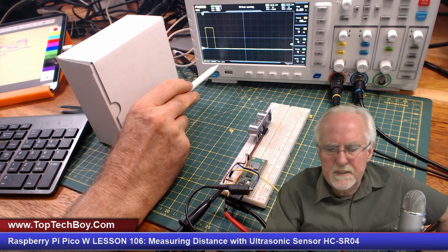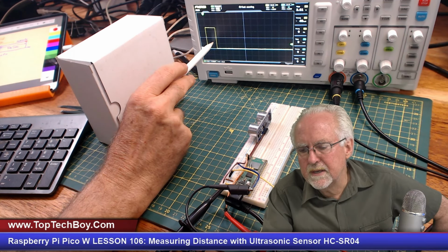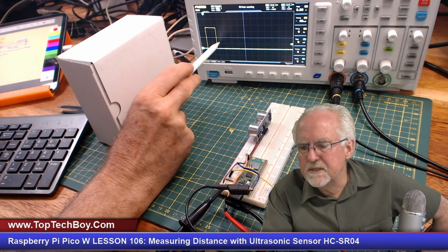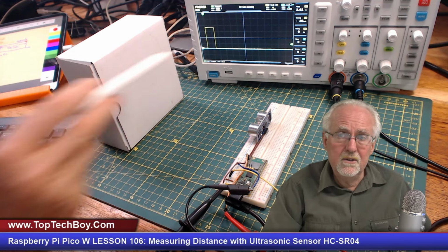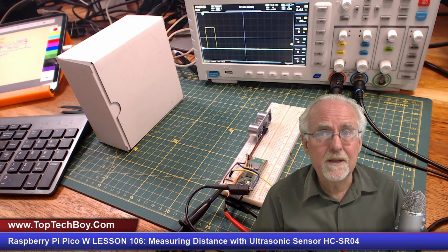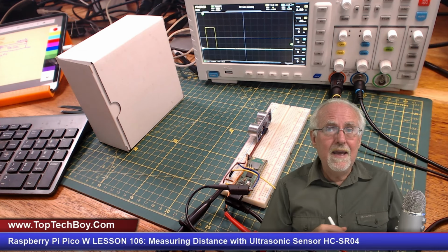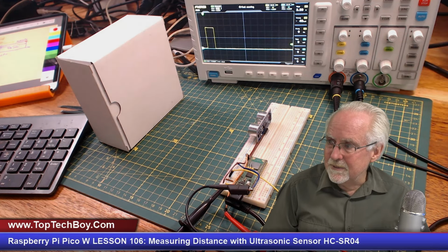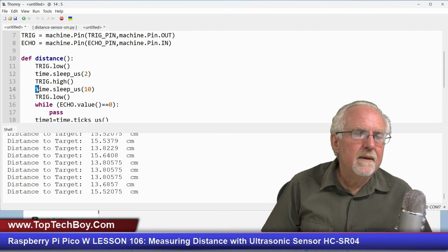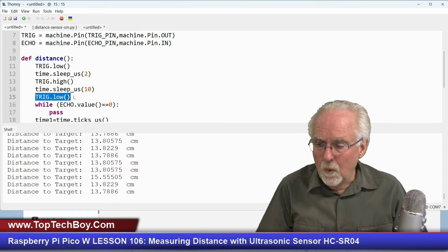I'm expanding this out and scooting it over so we can look at this trigger pulse. This is set on 20 microseconds per division. And it's jumping between 1 division and 2 divisions, and that's at 20 microseconds per division. So what trigger pulse am I actually generating? Between 20 microseconds and 40 microseconds. Why? Because MicroPython is lousy at timing. It's absolutely lousy at timing. And you can see over here, we did it perfectly. We said go high, then wait 10 microseconds and go low. But it stayed high between 20 and 40 microseconds.